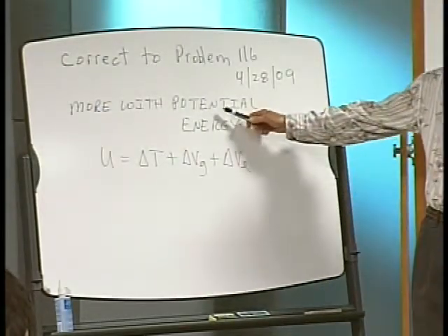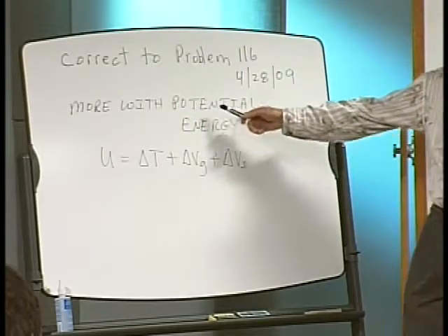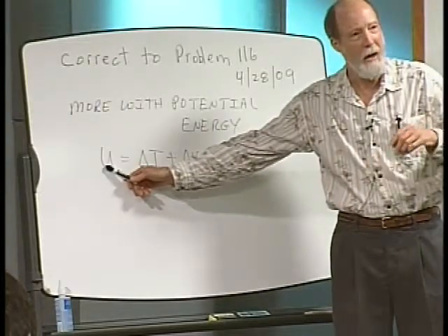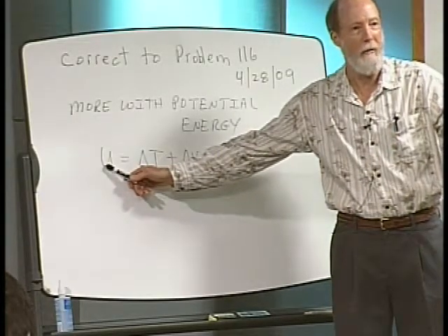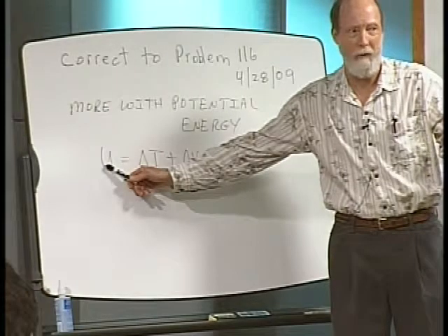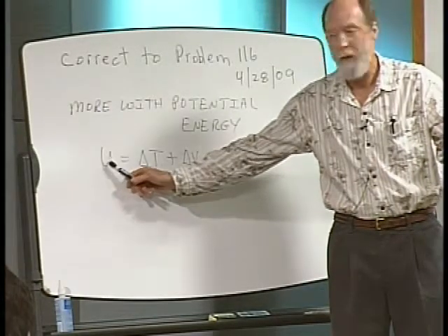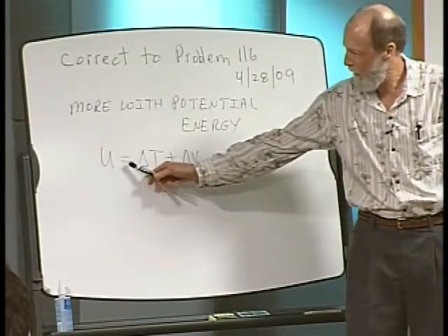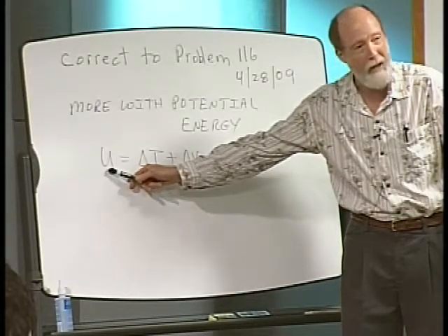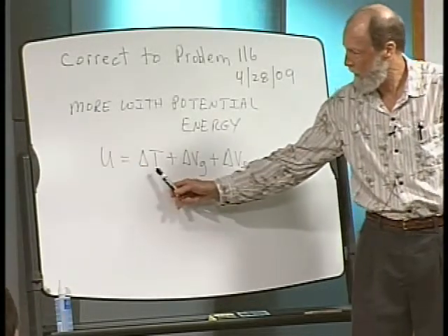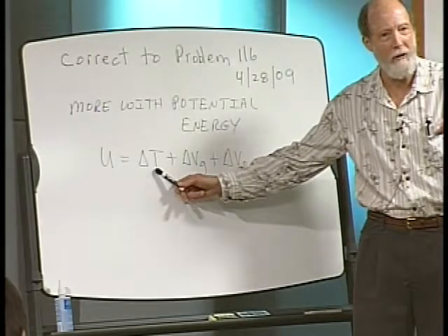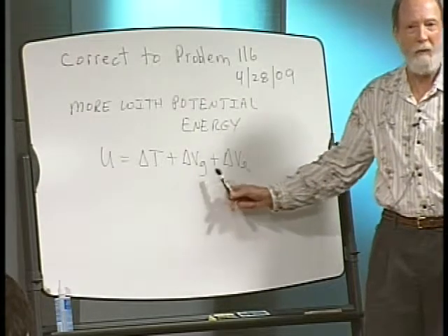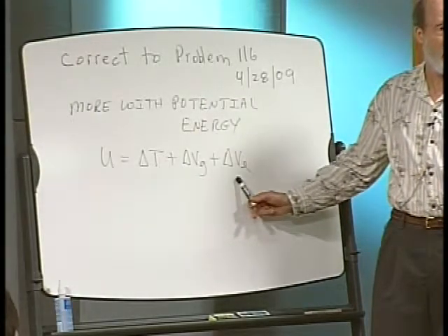Then what we'll do today is start working our problems using energy, where the work done by active forces other than gravity or other than springs is included in the work function over here on the left side, and over on the right side that sum of energy or work is going to be equal to the change in the kinetic energy, or that energy of motion, plus the change in gravitational potential, plus the change in elastic or spring energy.